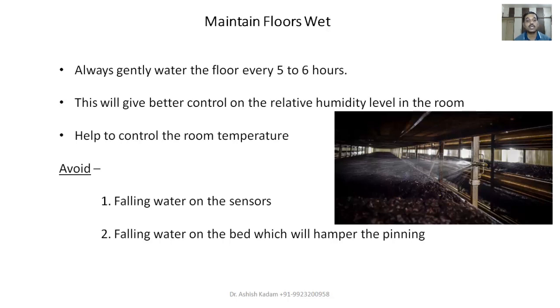And this will give better control on the relative humidity level in the room, and help to control the room temperature also. Avoid falling water when you are spraying the water on the beds, bags, or the flooring. The water should not fall on the sensors, because sensors are very costly. We have to take a lot of care. Falling water on the bed will hamper the pinning. So water also should not fall on the pins or the buttons. It should be very gentle.